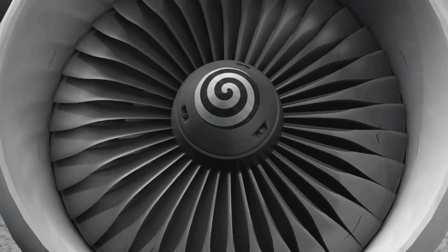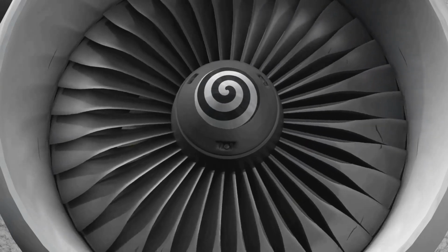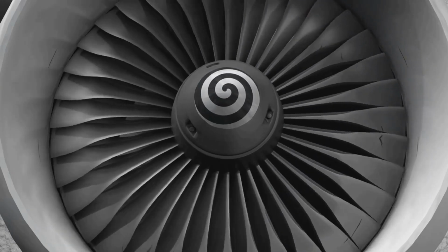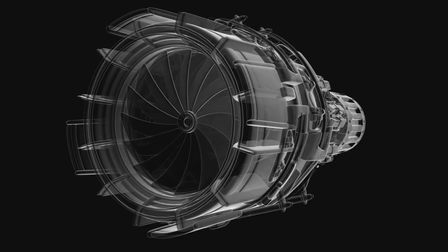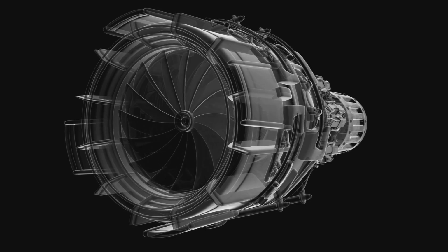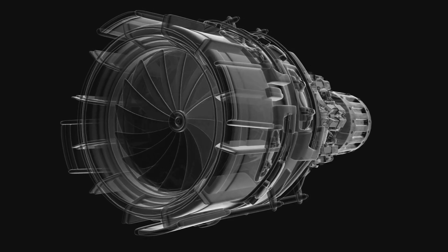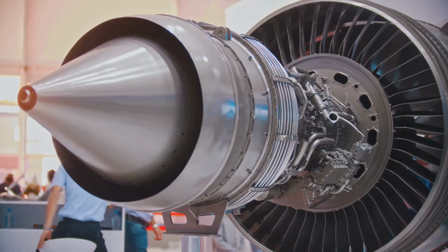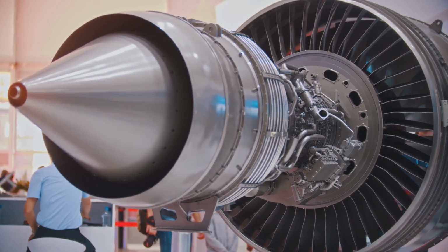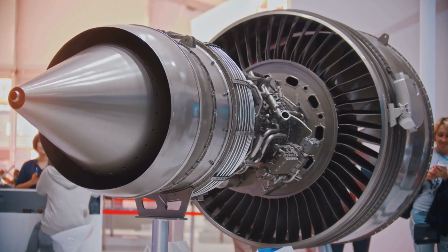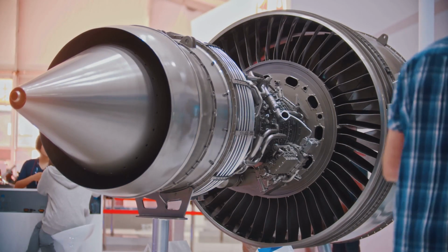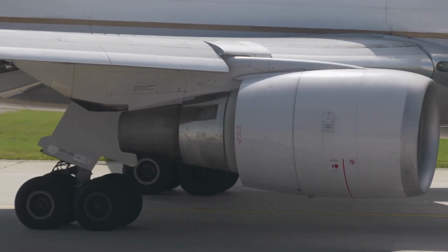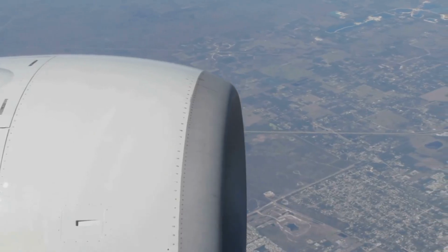Basically, turbofan engines work by using a large fan at the front to suck in and accelerate a massive amount of air. This air is split so that a small portion goes into the engine core to be compressed, mixed with fuel, and combusted, while the majority actually bypasses the core. The core's hot gases drive the turbines and the fan, while the large volume of bypassed air, or bypass air, provides most of the engine's thrust, making it fuel efficient and quieter.